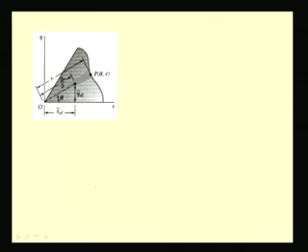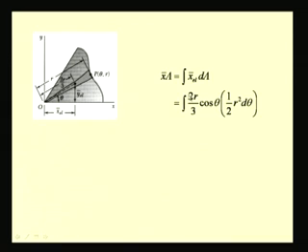We can also take other forms of elements, like in this example where we have a thin triangular strip which can be swept in order to approximate this area, and so we can define the centroids by taking these elements, where dA is the area of this element.